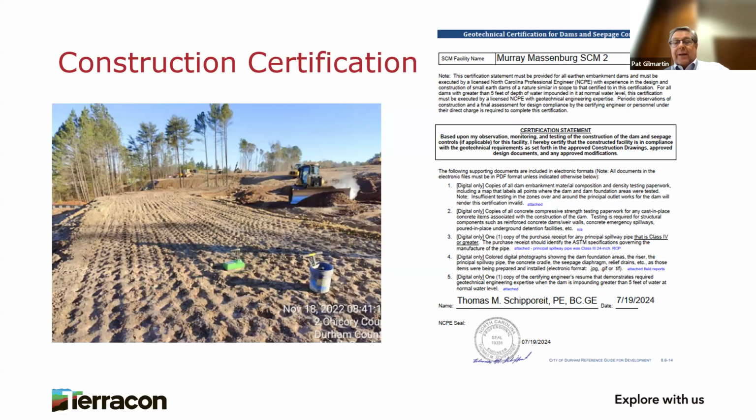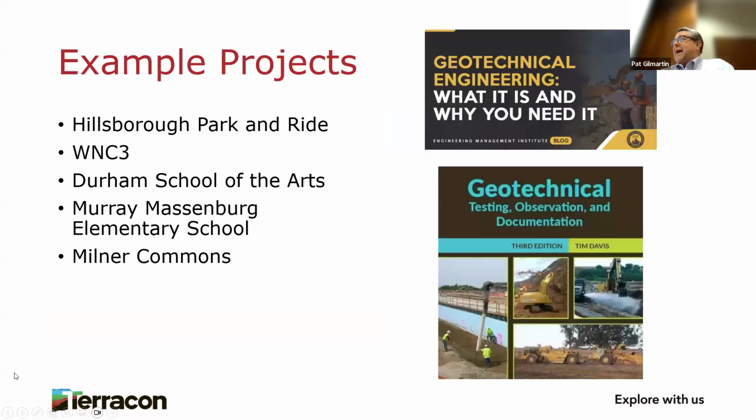It's not a good idea to wait till the end of construction to ask the geotechnical engineer for a certification if the geotechnical engineer was not involved with the project during construction. Kind of hard to certify it if you or the people that you work with weren't out there checking all the boxes and doing everything they needed to do. And I've been asked to and refused a couple times to certify ponds or embankments in Durham because the data just wasn't sufficient. But then we normally have to go back and do additional testing and try to see if it works anyway.